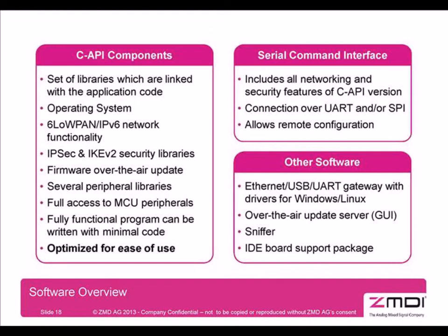Furthermore, if you decide that you have your own microcontroller and you want to interface with our modules, we provide a serial command interface. It's connected via UART or SPI. It allows remote configuration, and we provide some AT-like commands to control the module and to send packets.